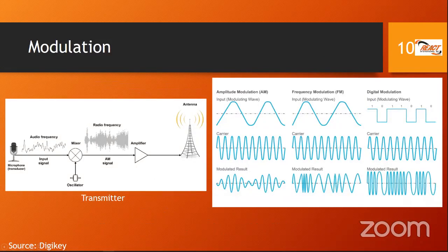We had discussed modulation previously, but we will look at it again. Remember that we are talking about using a radio to speak into the radio and talk to someone maybe within our country or outside of the country over the airwaves. So we have a microphone that generates an audio frequency. We have the mixer that we talked about and the local oscillator. And our audio frequency is added to a carrier and it modulates that carrier, and we end up with a frequency that is transmitted that is modulated by our voice.